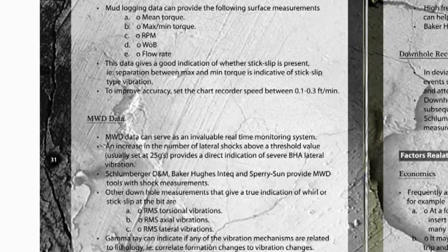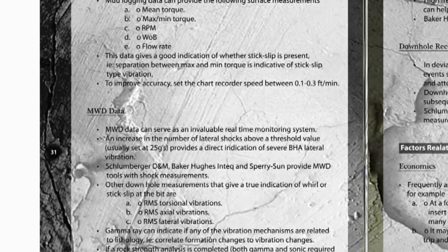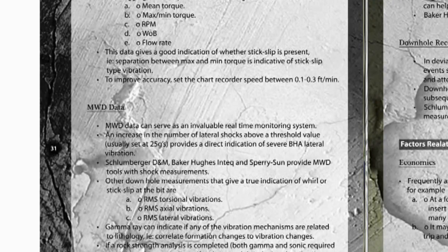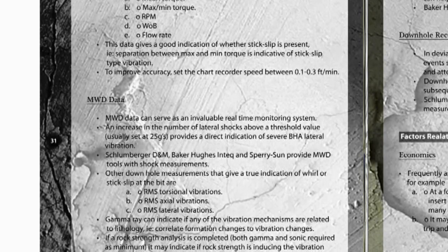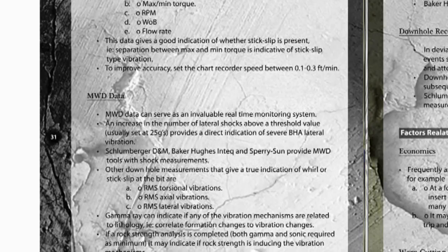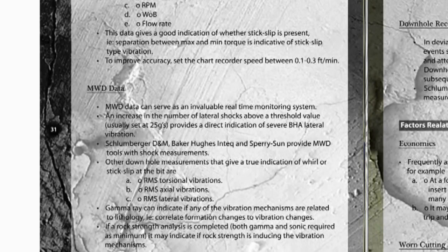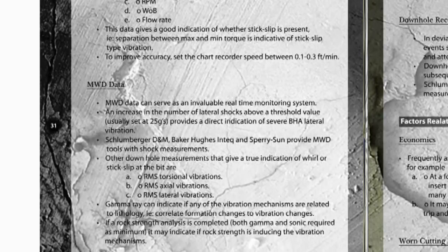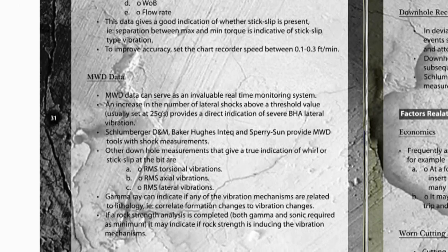MWD data can serve as an invaluable real-time monitoring system. An increase in the number of lateral shocks above a threshold value, usually set at 25 Gs, provides a direct indication of severe BHA lateral vibration. Schlumberger D&M, Baker Hughes Inteq, and Sperry-Sun provide MWD tools with shock measurements.